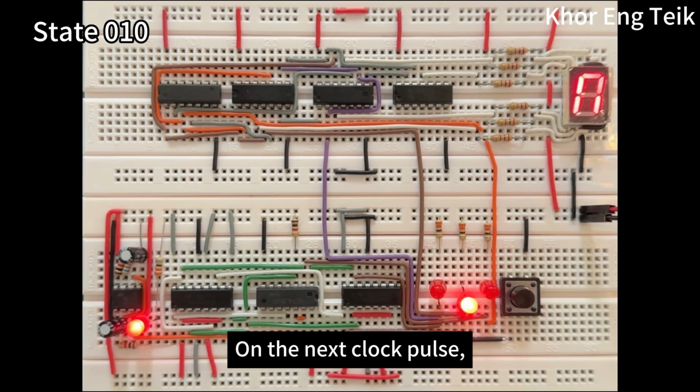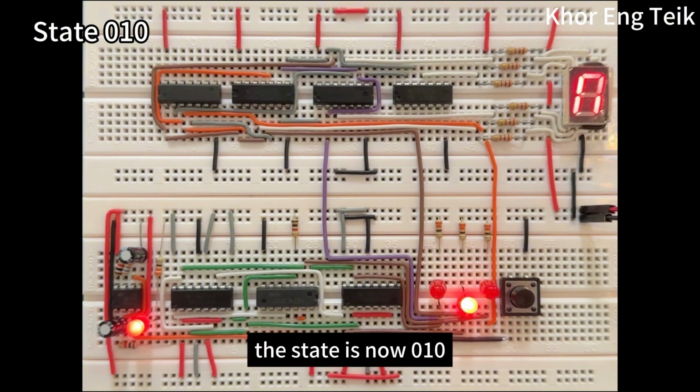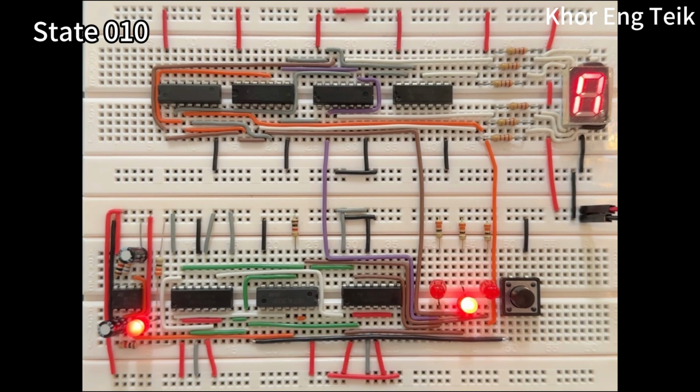On the next clock pulse, C toggles back to 0 and B toggles to 1. The state is now 0, 1, 0. The LED for B is on while C is off, and the display shows N.